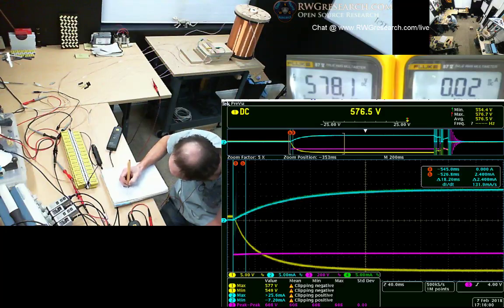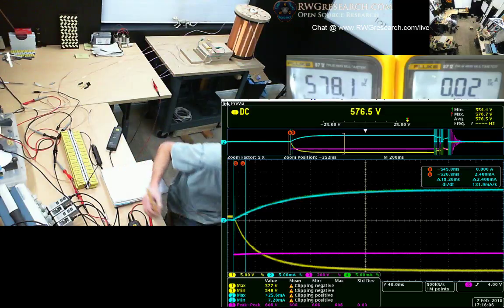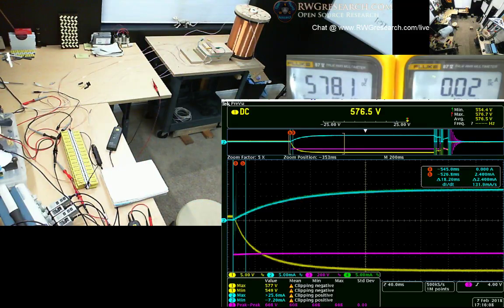So you need to know how many degrees that is. Let's see. You got that document? Yeah, I have the document. Hold on here. 600. Divide the time per revolution by the time required for the coil current to rise 20% as determined in step 4. This should be at least 10 times and less than 20.